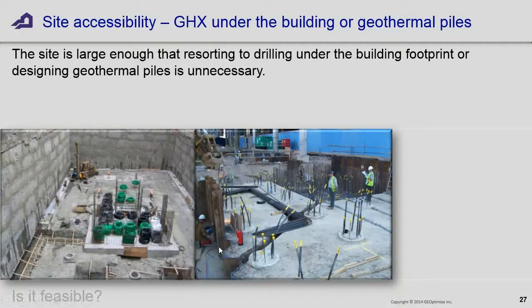I haven't seen a lot of this kind of work done where you've got the ground loops in the piles, and I've got pretty mixed feelings about the logistics involved in that. There's one project that I saw in Calgary where they tried to do the geothermal piles, and they lost about 15% of the boreholes simply because instead of pumping the concrete to the bottom of the pile hole with a tremie line like they should have, they just dumped it in the top, and that wrecked half the pipes. So with that kind of logistics, I'm not convinced that geothermal piles are cost effective. Do they work? Sure they do, if they're done right. But I'd guess they're probably more expensive than simply drilling between the piles.